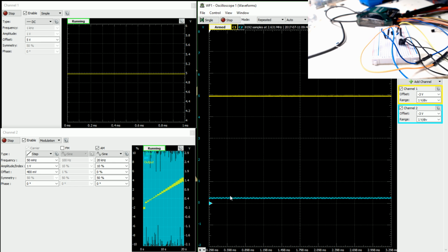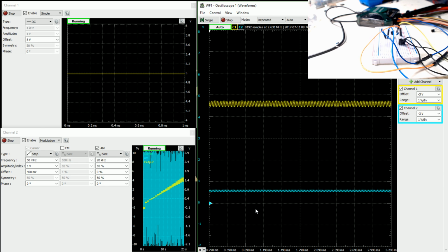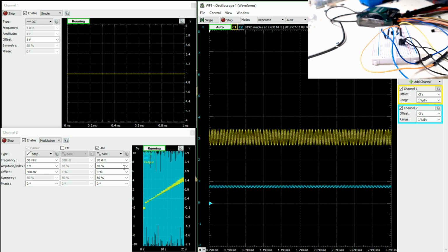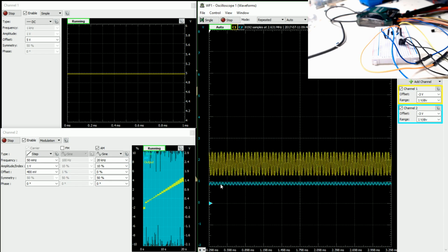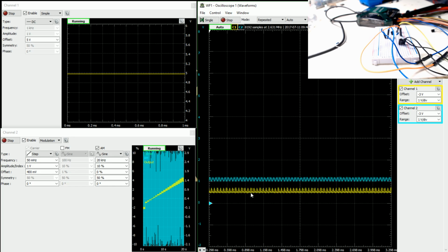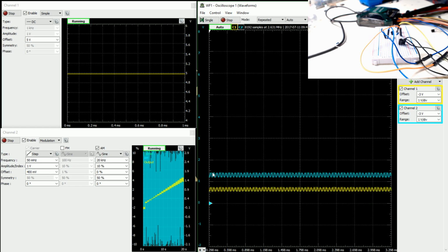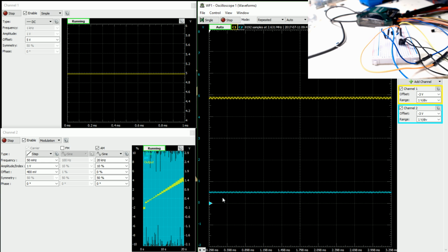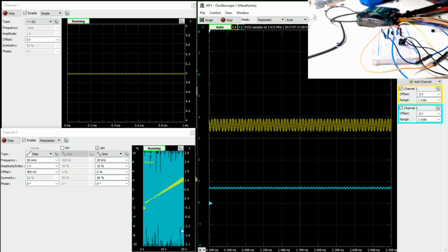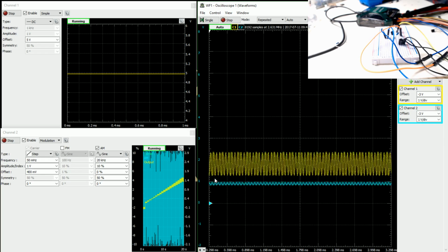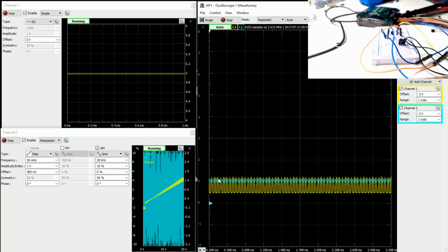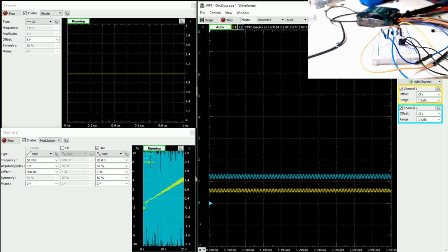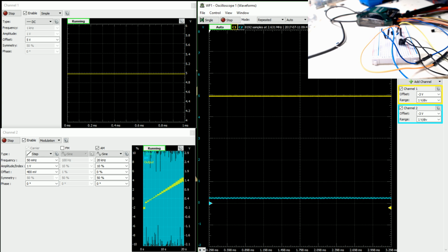Okay, so let's see it one more time. And there's not really a way to pause this as far as I can tell. So you see right about at 900 millivolts, that's about our maximum amplification. Oh yeah, okay, so it was that. So as we keep going up past 1 volt, you see that the amplification starts to die off, and that's because the contribution of the current from the base to the emitter and the contribution of current from the collector to the emitter starts to normalize, and so we really lose that amplification factor. Once it goes past about 1 volt, it's not properly biased anymore, and that's what we're really getting at here. So if, let's see, I don't really know how to make it pause at the proper place.